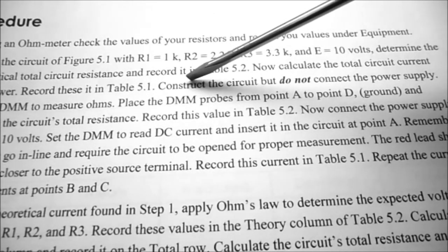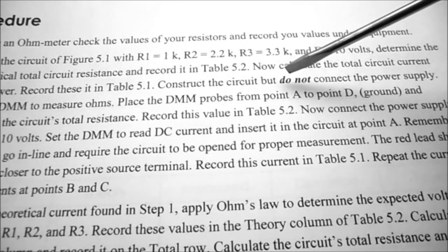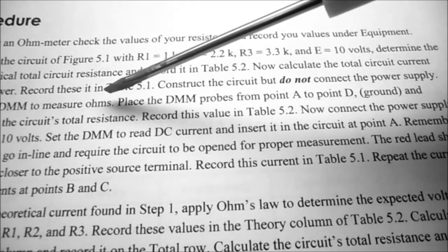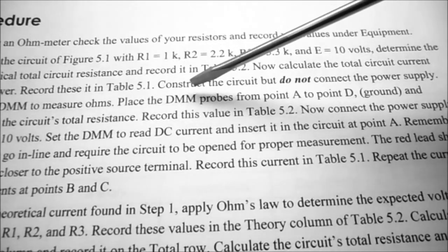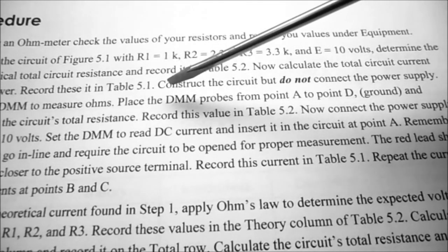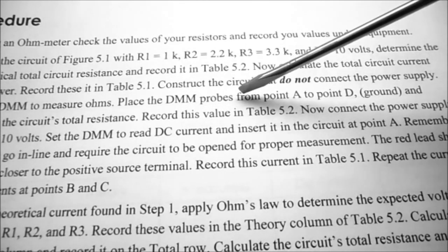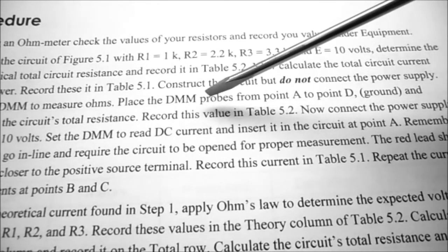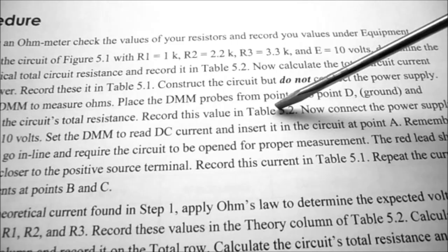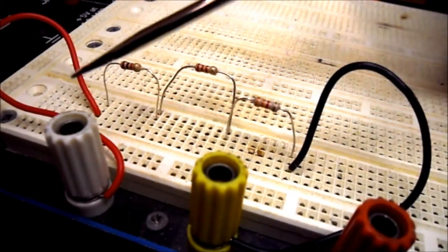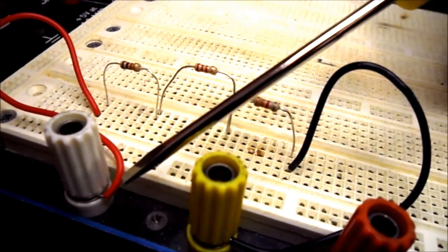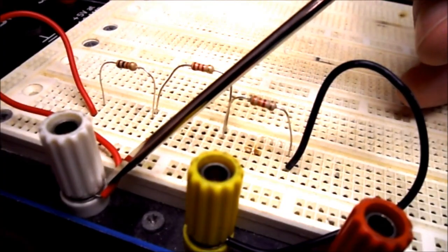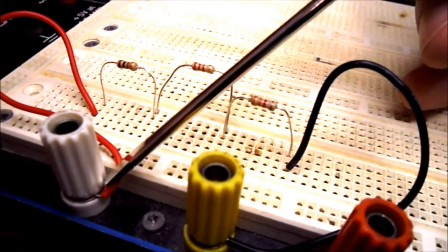So under Procedure Step 2, we're now going to construct the circuit, but do not connect the power supply. We're going to set our DMM to measure ohms, and we're going to check the total resistance of the circuit. We're going to place the DMM probes from point A to point D, and we're going to measure the total circuit's resistance, and we're going to record this value in Table 5.2. Now I have one binding post connected to the red lead, and you can see I've left just a little